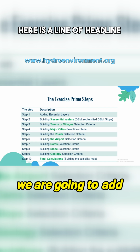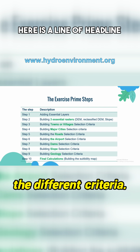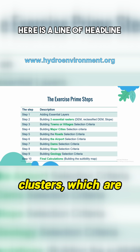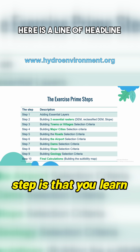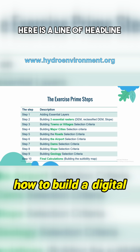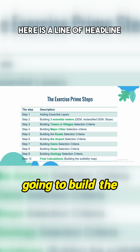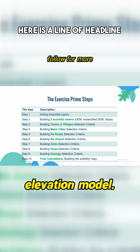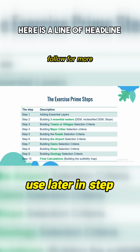In step number 1, we are going to add the essential layers based on the data we have collected for the different criteria. In step number 2, we are going to build 3 essential rasters, which are the digital elevation model and reclassified digital elevation model. The purpose of this step is that you learn how to build a digital elevation model based on a contour map, and also we are going to build the elevation selection criteria in this reclassified digital elevation model. And lastly, we are going to build a slope map,